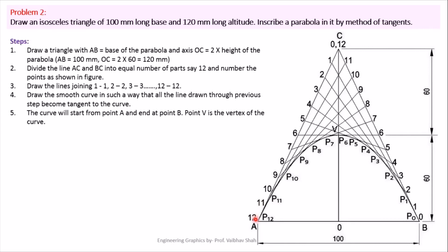So you have to use your pencil and draw a dark curve to highlight this profile traced out by these tangent points. And after that you have to mark these points P12, P11, P10, P9, P8, 7, 6, 5, 4, 3, 2, 1 and P0.